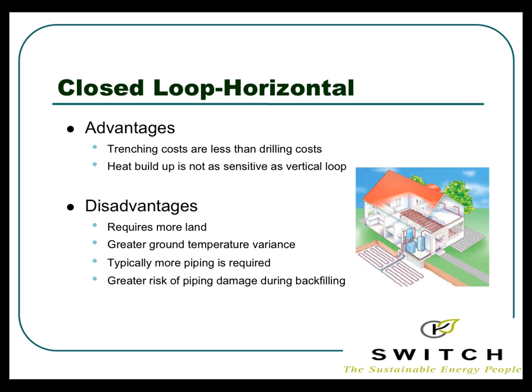Disadvantage on a vertical loop, of course, though, is it's very costly to drill holes in the ground. And that's going to be dependent on what we're drilling into. Are we drilling into a sandy environment, a clay environment, a rock environment, right? We move towards Gananoque, we're going to hit the shield. We're going to be drilling directly into rock. Backfilling requires special material and skills, and we also have a potential for a heat buildup. We're dumping that waste heat into the ground in the summer time. We can affect the performance of the equipment if we can't dissipate that heat out fast enough.